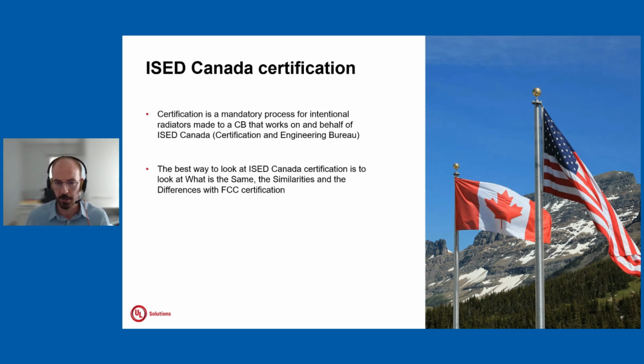First of all, there is going to be testing in a lab. This lab needs to be obviously accredited against Canadian standards. Once the testing is done for radio and EMC, you will move these reports to a foreign certification body. A foreign certification body, or FCB, is the certification body that will review the documentation, review the reports, and send it to ISED Canada, and it's going to be ISED Canada in this case who will issue the certificate and not the certification body. So UL as TCB and FCB are part of the review phase.